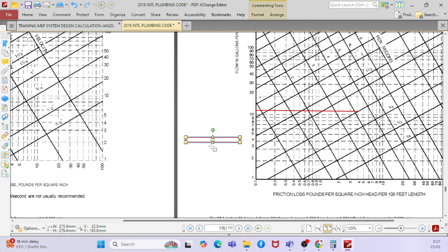Friction means what? For example, whenever the water flows in the pipe, it cannot flow at the same velocity. Say there is a velocity here; the same velocity you cannot expect here, correct? There is a slowdown because of the friction in the pipe material. So that is the pressure drop. Pressure drop means when the water flows through the pipe, it cannot flow with the same velocity. There is a different velocity here, and a different velocity here. Or you can say a different flow rate.